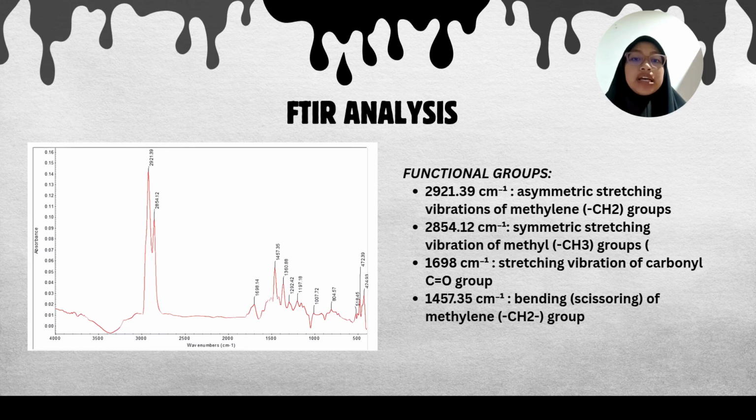Next is the peak at 1698 per centimeter, which is attributed to the stretching vibration of the carbonyl group. Since the sample used is unused lubricating oil, the presence of this band is likely associated with oxygen-containing additives or ester-based compounds rather than oxidative degradation products formed during engine operation.